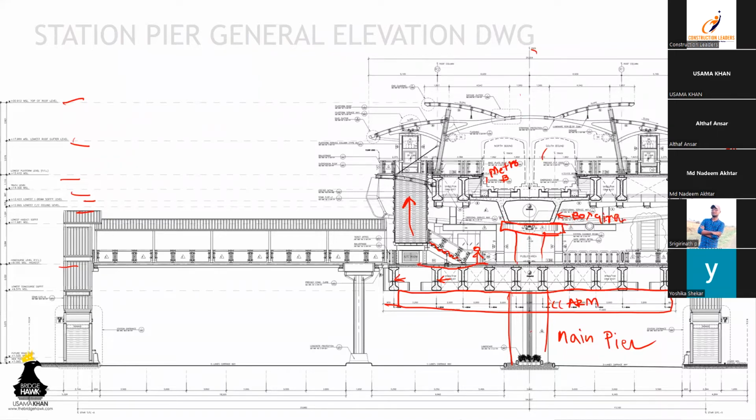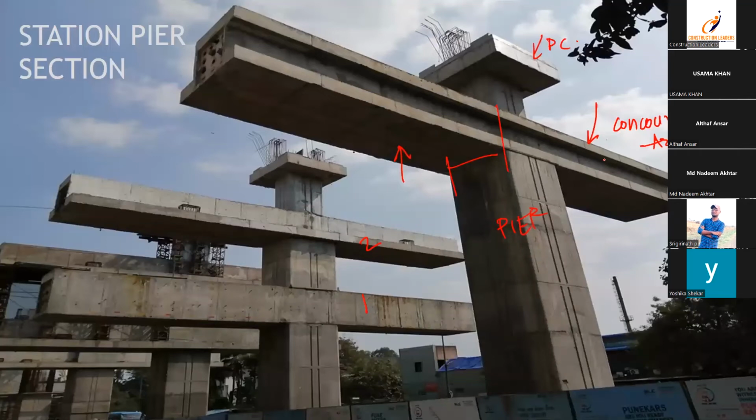And finally, over here is a separate arm, which is a platform arm. So this is typically the platform. This platform arm is supporting the I section, which is supporting the deck, which is supporting the pedestrian. So the pedestrian is going to the metro from over here. And as I said, all these architectural elements have to be supported. These generate huge loads, especially wind loads. So these are station piers as constructed.